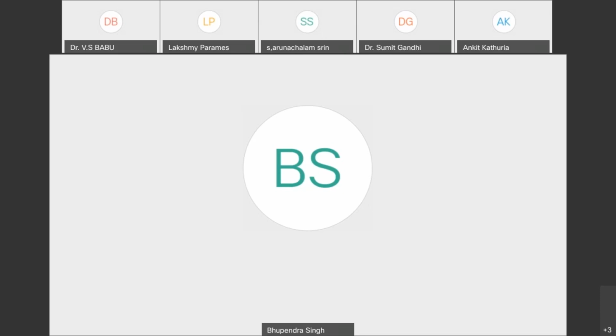So that is why the viscosity grade that we are considering at the moment is not adequate to accommodate all the pavement conditions. That is why it is very important to move on to performance grading. Like we can see in the performance grade, they have taken PG 82 also. So they have taken up to a pavement temperature of 82 degrees Celsius. That is one of the limitations of viscosity grading, and that is why we should move on to performance grading, so that we can accommodate all types of pavement conditions.